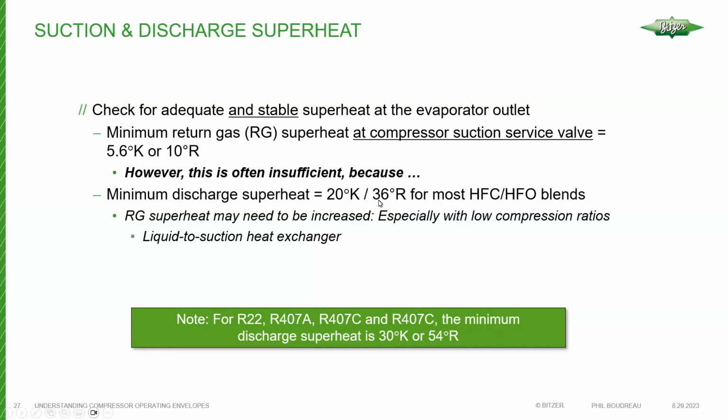Well, this is easy to do. When you go into the software and you're selecting a compressor, you can try increasing your return gas temperature or return gas superheat, and you'll see that the discharge temperature will follow. It will increase as you increase the suction gas temperature.